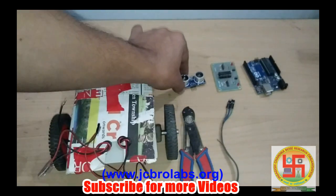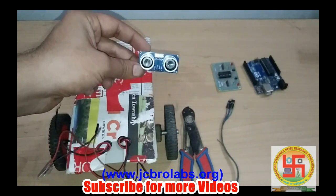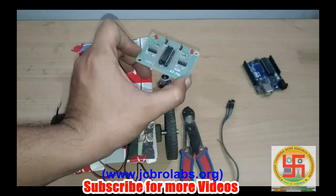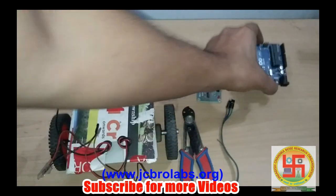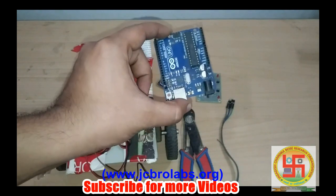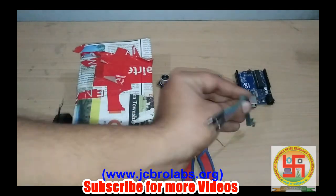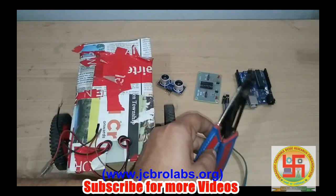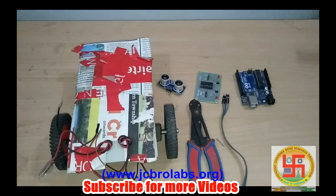Obviously we need an ultrasonic sensor to measure the distance of the object, and then we will need this L293D motor driver circuitry. So here we have it, and we have our processor, that is, right now we will be using this Arduino Uno. Apart from this hardware, we may need some jumper wires in order to connect several components, and we may need some other toolkit in order to arrange everything. So these are the minimum hardware we may need.